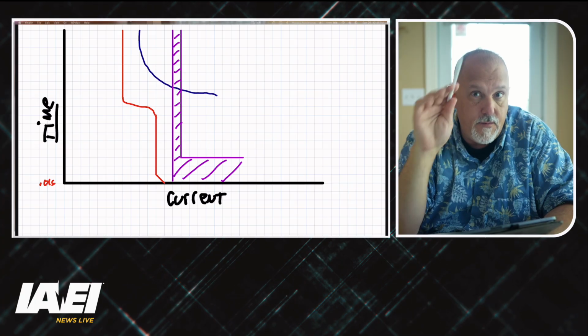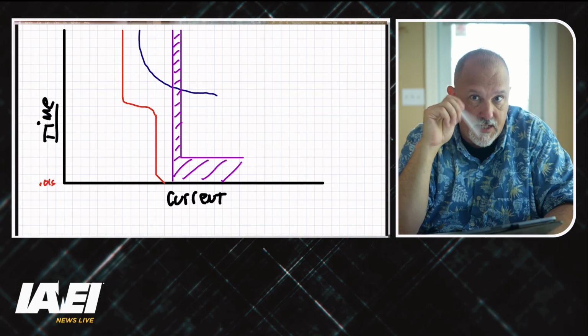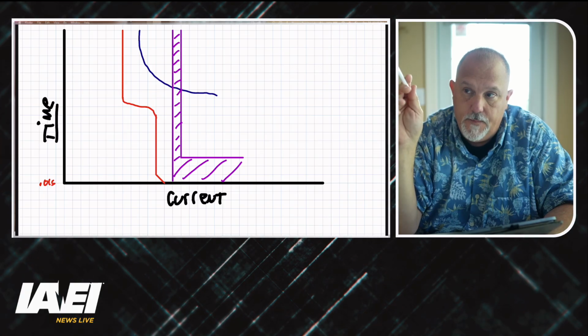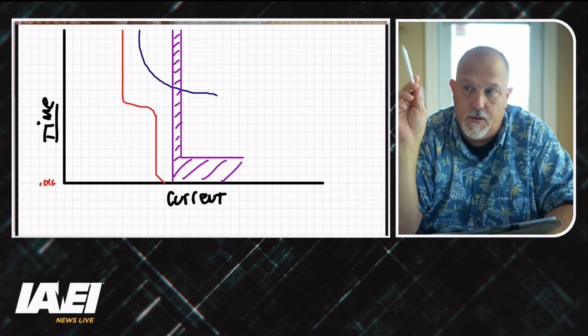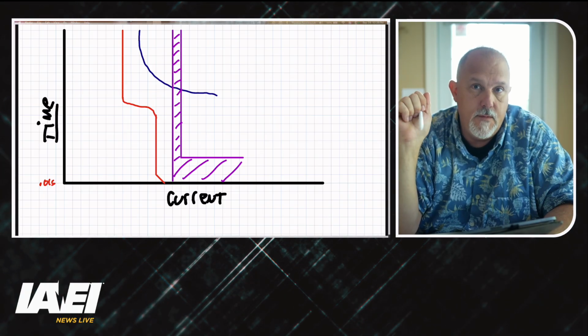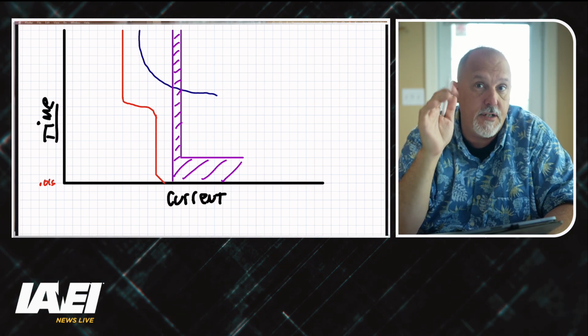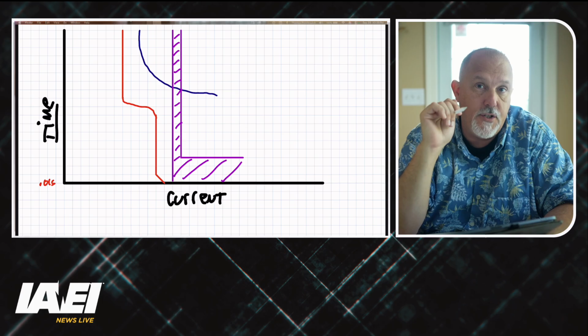And that's looking at the 75 or the 60 degree C column, making sure that your overload protection provides the protection of the conductor and the termination. And again, the termination more than likely is your weakest link.